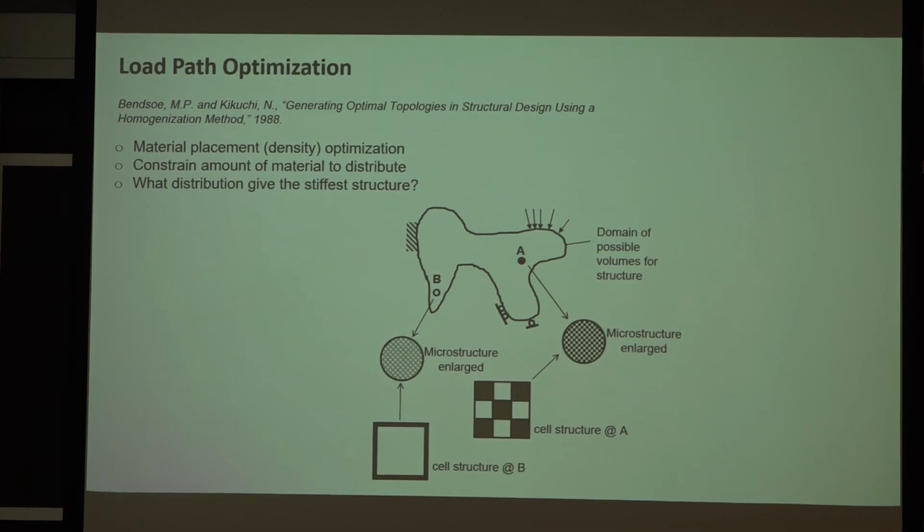Okay? Then they say, if I want the most efficient load paths through this, I'm going to calculate the aggregate strain energy for all these elements, and I'm going to search the design space of these elements where density is the design variable, and I'm going to figure out where I get the lowest strain energy. So let me repeat that again.